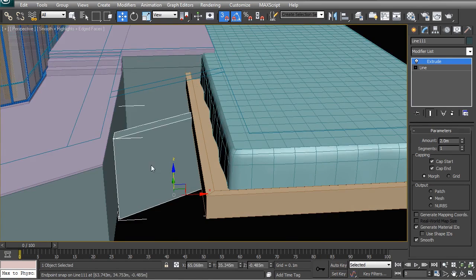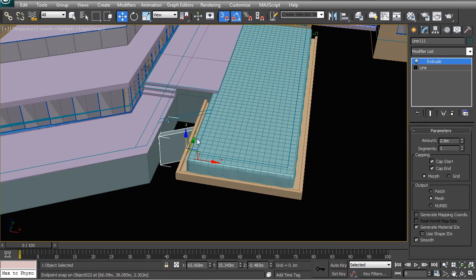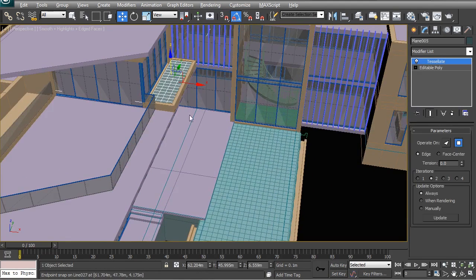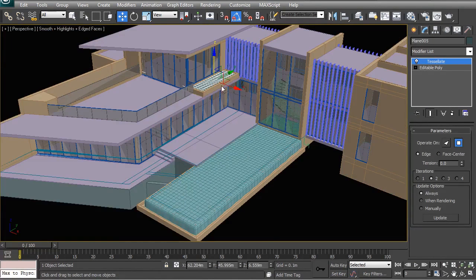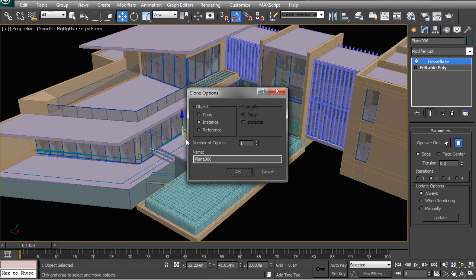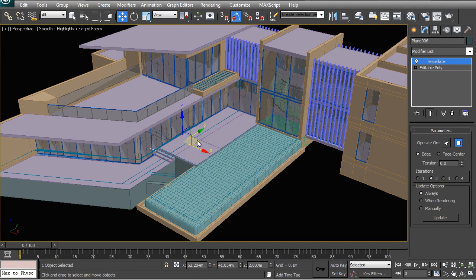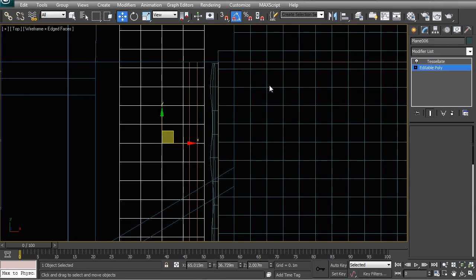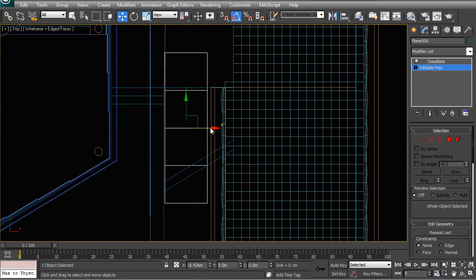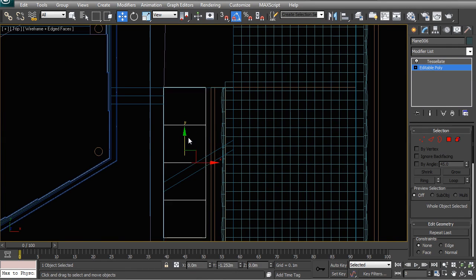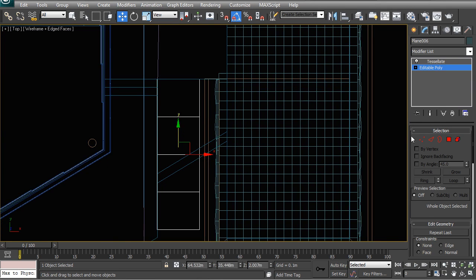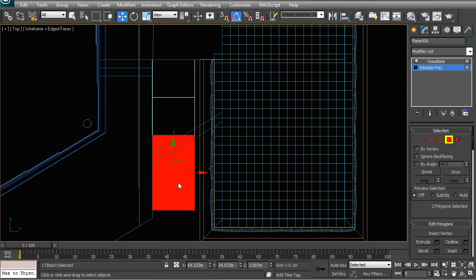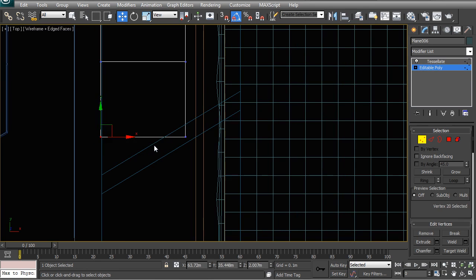So lastly, just before we finish this lesson, we are going to make a small patch of ground, and what I suggest is that you just take already made or existing pieces of that terrain, and you can basically just move it downwards. Do everything by eye. Make sure you copy it, don't instance it. Move it into the right place, and you can basically just start to edit those polys there. You can also redraw it. There's nothing wrong with redoing, but I always like to rather copy and modify. Just out of principle, it's often much easier. You're always guaranteed that things are the right color, on the right layer, and have the right modifiers in the stack.